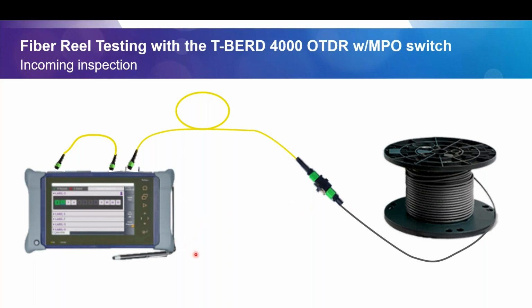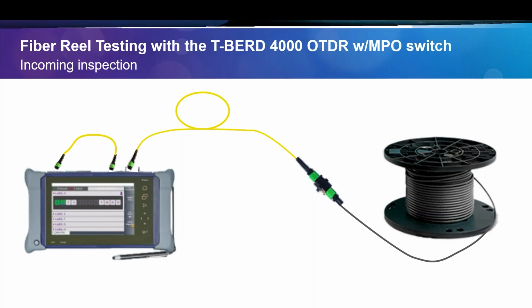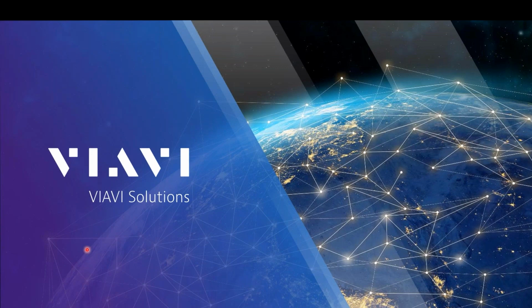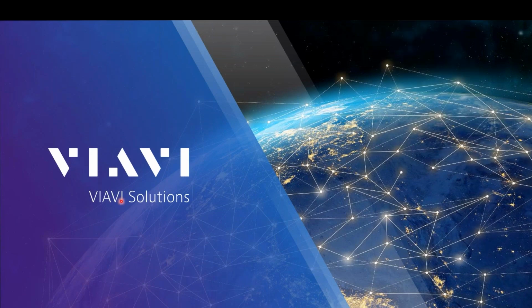So that's pretty much it on the MPO. Again, we went through the physical characteristics: keys, pins, unpinned, polarity types A, B, or C. And then single mode is angled, multi-mode is flat connectors. Inspection is critical when dealing with MPO cabling.